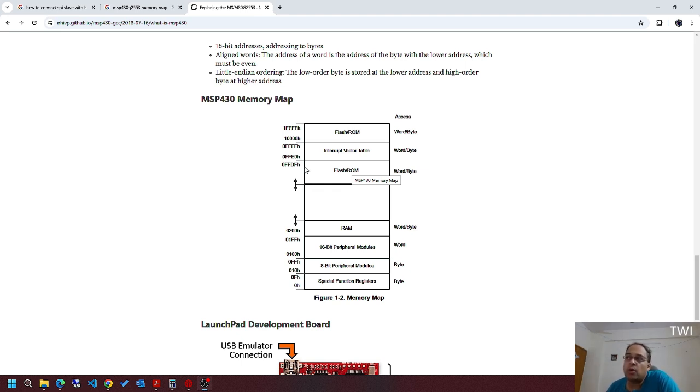And apart from that, you also have to do some changes in the interrupt vector table, because once your controller comes out of the initial PUC, that is power on condition reset, or you can also say POR, power on reset, there are certain vector locations from where the address is fetched by the program counter. Now ideally, if you're using CCS, Code Composer Studio from TI, they have pre-initialization codes which will execute your code from C000 location, but definitely you can customize and change it.